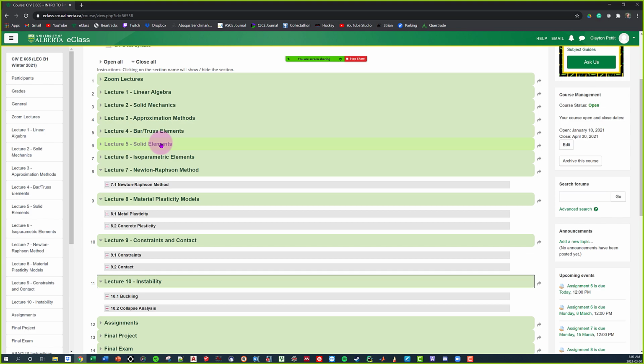That's okay. Basically what happens is when we're dealing with those bar elements as well as our solid elements, we said that they are C0 continuous, meaning that as long as the displacement is continuous between elements, I'm happy. I don't care if the stress derivatives are discontinuous or anything like that. As long as that displacement was good, I'm good.